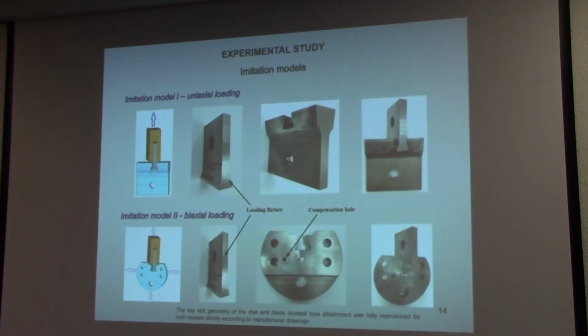The next part of our study is concerned with manufacturing of imitation models and loading fixtures and further testing of imitation models. Both models were produced from titanium alloy, and the key slot geometry of the disk and blade dovetail attachment was fully reproduced for both models strictly according to manufacturer drawings.